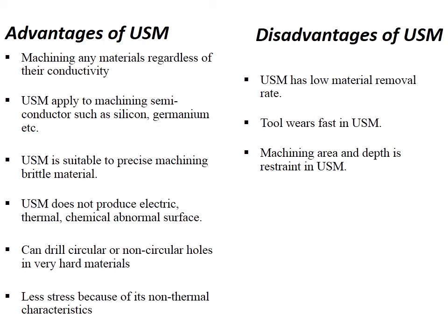So the advantages and disadvantages, every coin has two sides. So let us first discuss the limitations. Now we have a brief idea about the basic mechanism or principle of ultrasonic machining. The disadvantage is that, as you know, the material removal rate is quite low. Tool wear is fast because the tool is made of lightweight material having low hardness compared to the workpiece, right? So it wears fast in USM.